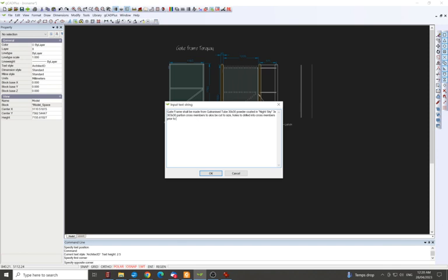Prior to powder coating, it's always better to drill the holes first and then powder coat. All dimensions to be confirmed prior.